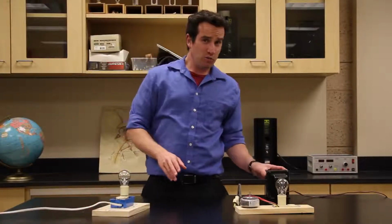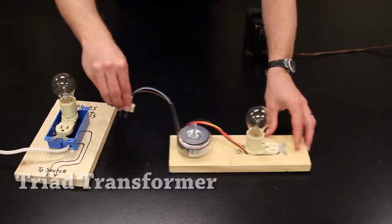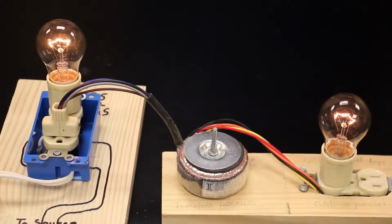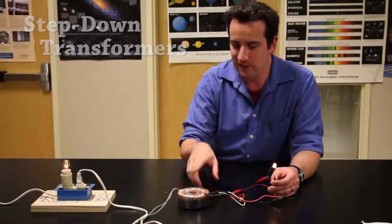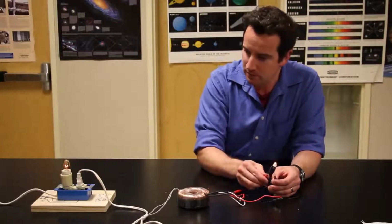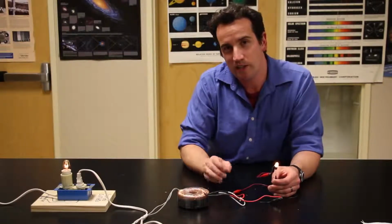If you don't already own an isolation transformer, you can buy a small triad transformer for about $20. Its only shortcoming is it has a small power rating and should only be used with bulbs of less than 25 watts. If you have a high quality step-down transformer like this 10:1 toroidal, then you can still do the demo, but you should work to ensure that your light bulbs have the same wattage. Toroidal transformers have excellent flux linkage, and so they tend to be more efficient.